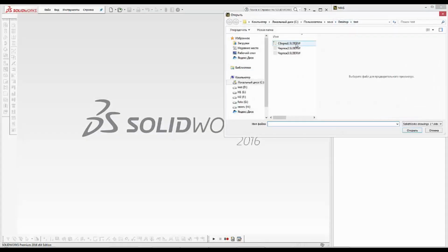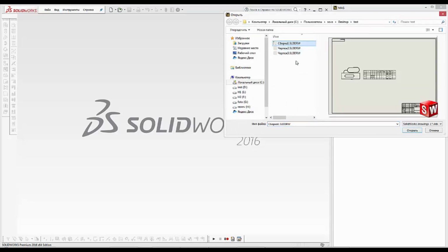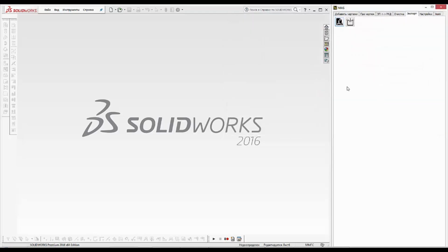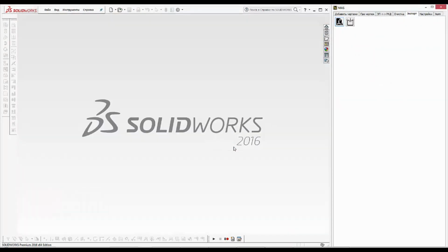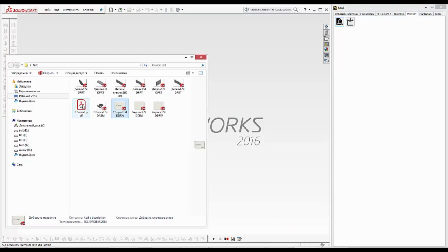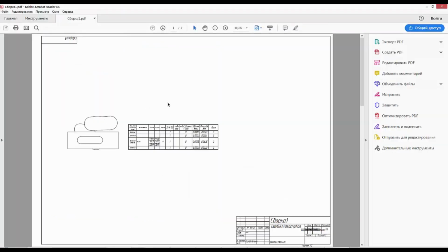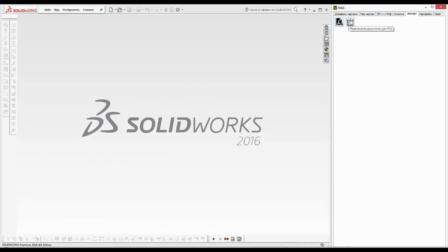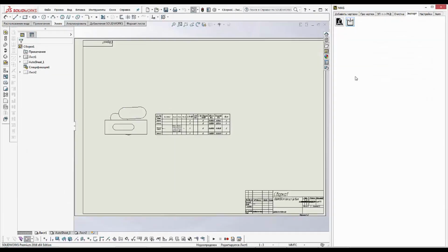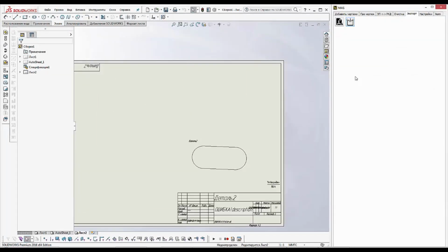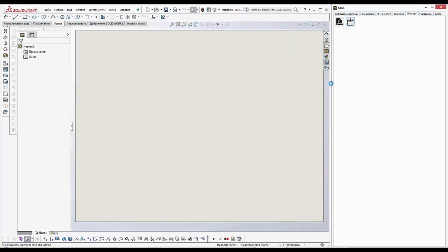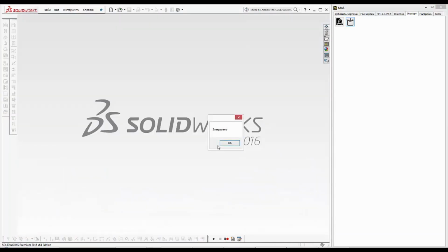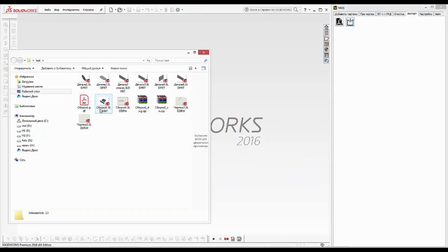The next export function is designed to prepare documentation for uploading to a CRM system. There are two preparation modes here. The first mode is to export various documents to a single PDF document. The next export mode first also prepares a PDF document, then prepares DWG files. And then the program archives the exported documents together with SolidWorks files.